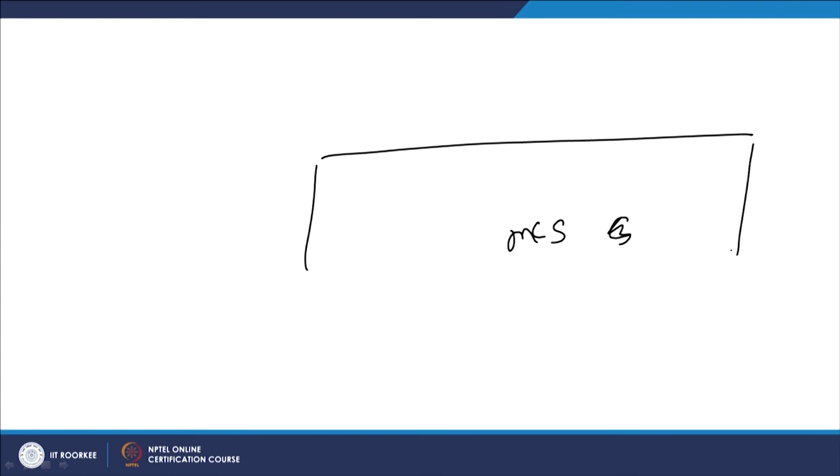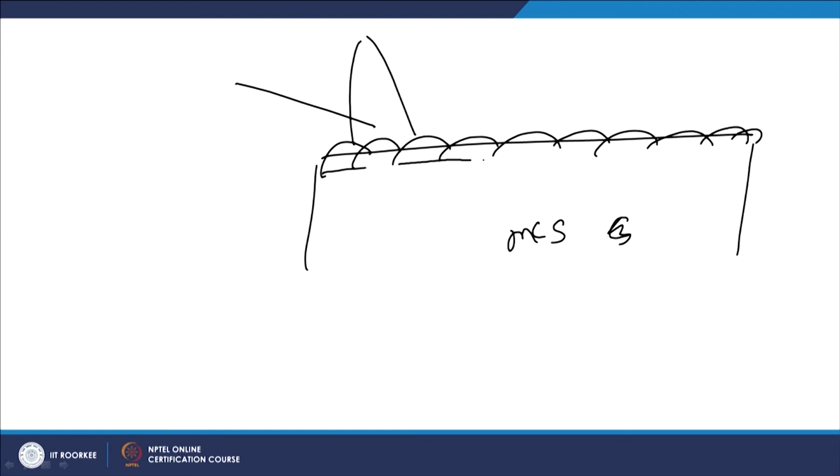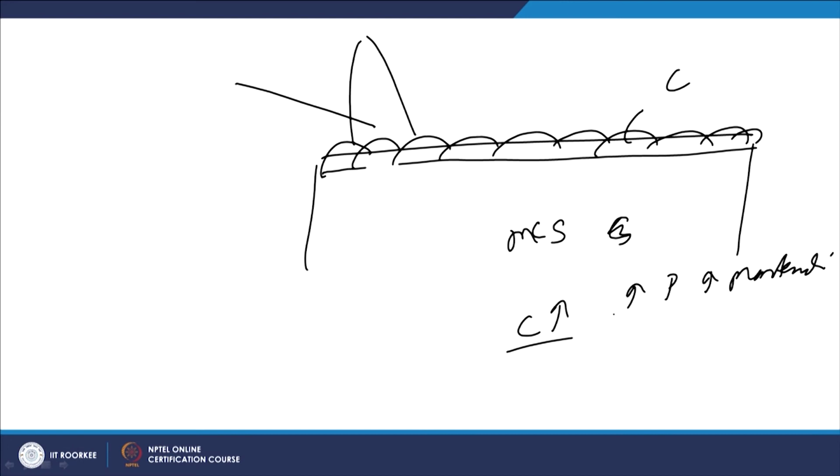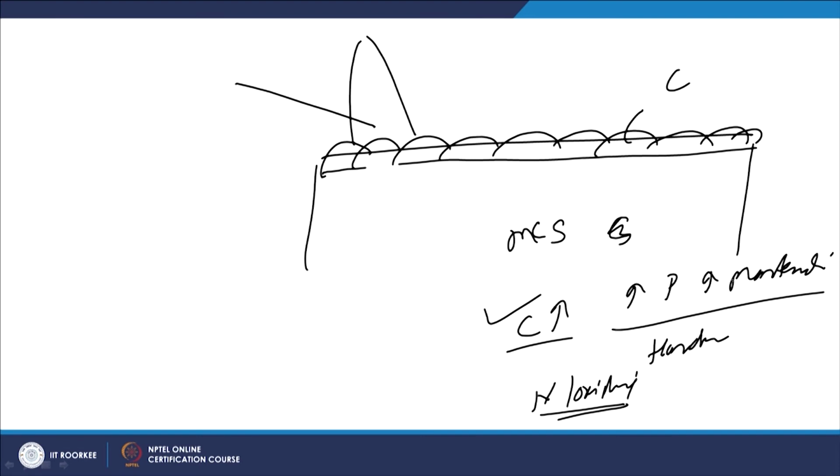So, like say if this is the medium carbon steel which is being modified with the help of the gas flame, and we are feeding the electrode, and a weld bead is being developed like this. So, the composition of this weld bead will be richer in carbon content if we are using carburizing flame, and we know that increase in carbon content in the steel in general leads to the increased percentage of the pearlite or increased percentage of the martensite as per the kind of cooling rate, and both these factors will be increasing the hardness of the weld surfacing as compared to the case when we use the neutral or oxidizing flame.